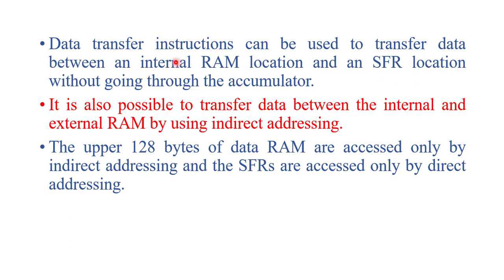So using data transfer instruction, we can transfer data between the internal 128-byte RAM location and the special function register area without using the accumulator register.